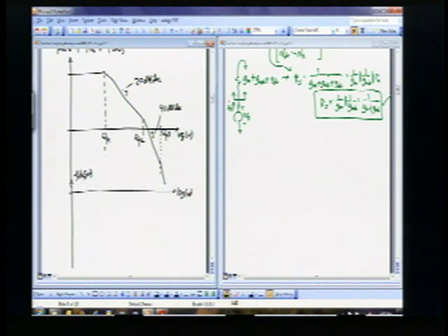Okay, first thing you want to do is project down where all these poles are located, because those poles shape the transfer function for this circuit, and will also shape the magnitude transfer function, and will also shape the phase transfer function for this circuit. And so what do you remember about how you do the phase for this? Do you remember any certain rules from your Bode plot days, which is maybe EE40 or 105? Did you do Bode plots in 105? Yeah, you did. A decade before a pole, you start going down at 45 degrees per decade. Yeah, that's right.